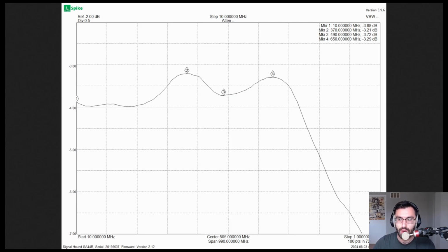Because not only are we not trying to represent perfectly a signal, which is what sin x on x does, and that assumes the signal is actually fully below your Nyquist frequency, which it is not. On top of that, we also just don't have all that much bandwidth below Nyquist. So that's why it looked really good on those other metrics, but when you actually test it across all the frequency range, you get this.